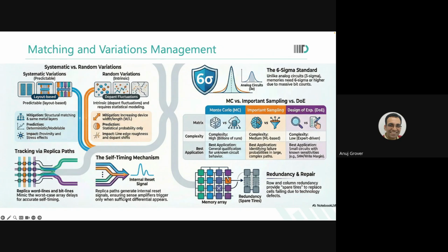What we are saying is that SAN over here should arrive before precharge reset. That's all that means. This you can handle. Handling this race condition is in your hands.